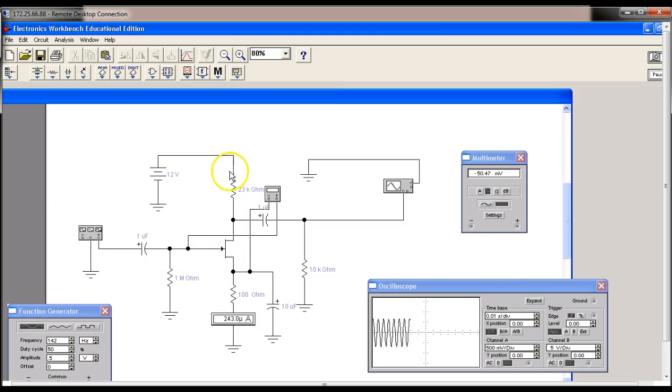So this would be what we call a common source amplifier. The common source amplifier, of course, has a high input impedance. It has a moderate output impedance. The input impedance, if we didn't have this guy right here, it would be infinite. And of course, the higher the input impedance is, the more noisy the amplifier becomes also. So this gives us a way of setting an extremely high input impedance, but not making it infinity.